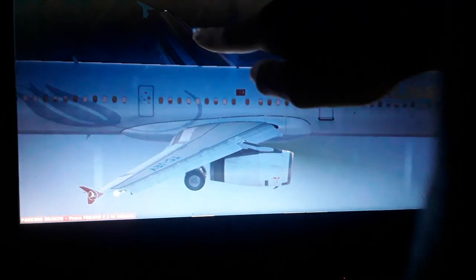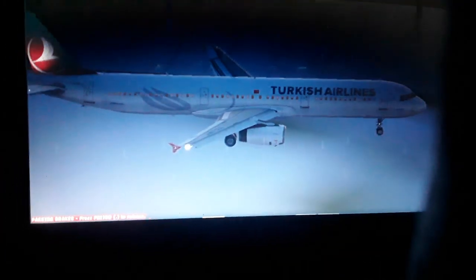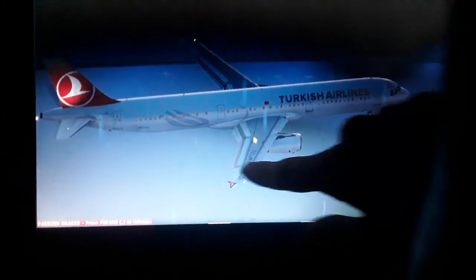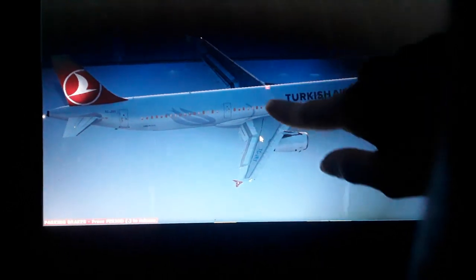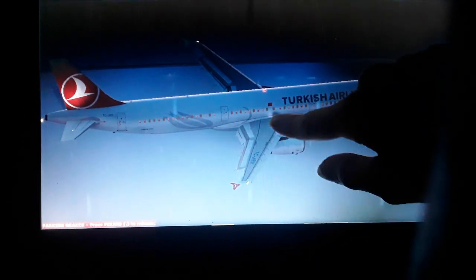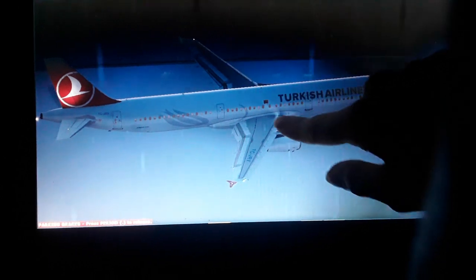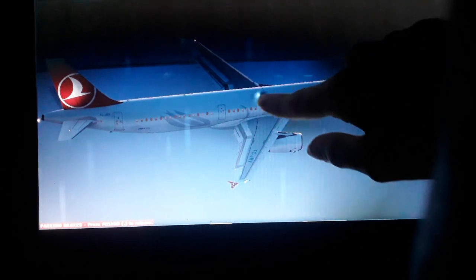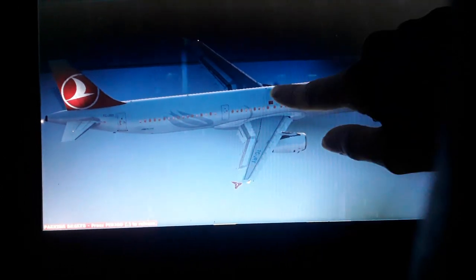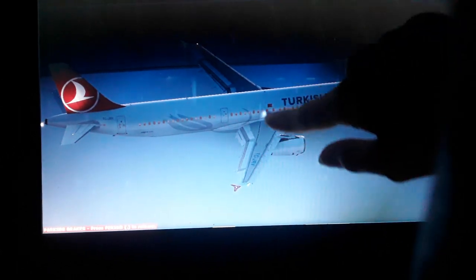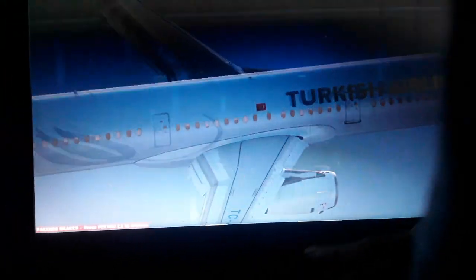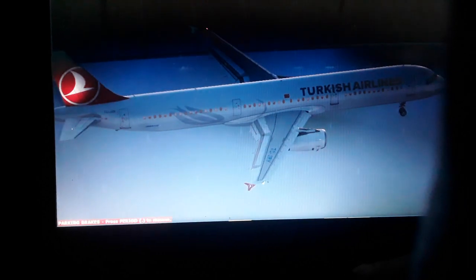This is the mean aerodynamic chord where the maximum aerodynamic lift occurs above the wing. It's also the position where the center of pressure of the air above the wing is, and also where the stall occurs, where the airflow of the air mass becomes detached from the top surface of the wings when you have a stall in an aircraft.